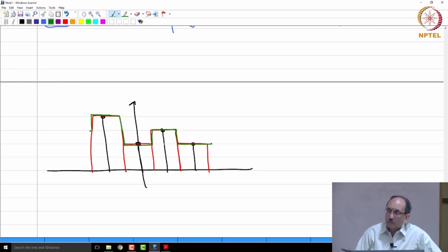Clearly that works because all your cell phone is working on samples. Telephony samples were transmitted at 64 kilobits per second, and yet at the receiving end you are able to hear continuous time speech, and clearly impulses are not transmitted. Impulses are not transmitted because, first of all, impulse is a theoretical construct, and impulse has infinite bandwidth, right. If you transmit impulses, a train of impulses through a channel, the channel is typically a low pass filter, it will band limit the impulse train. Therefore, all these are only theoretical constructs.